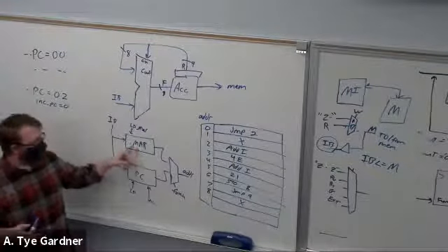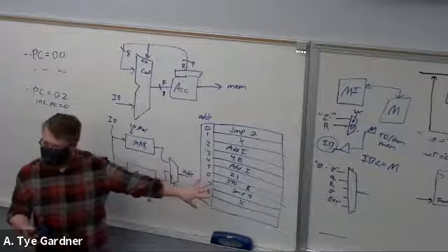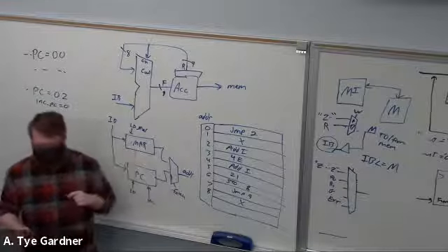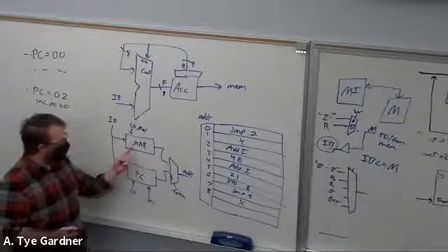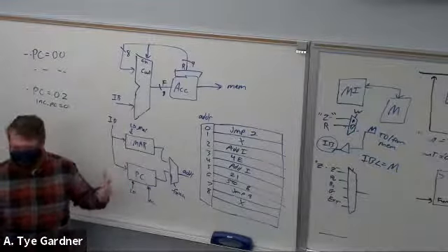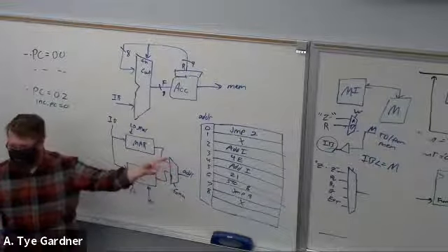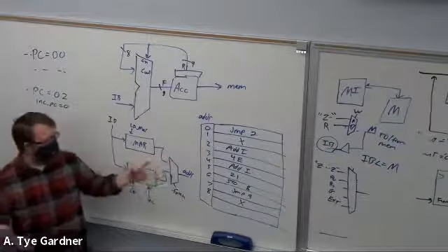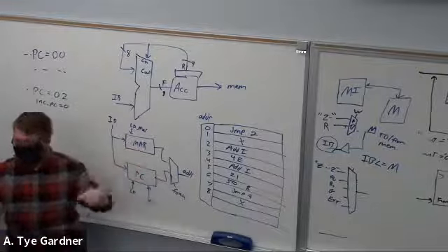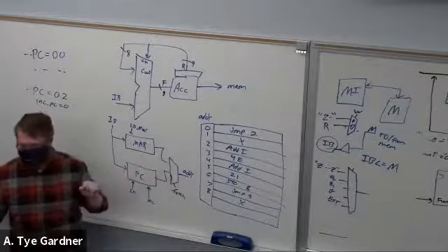And maybe we could also store that address somewhere if we wanted to go back and do it later, right? We can store the MAR if we wanted to. Not from the MAR, we'd have to store it at the same time we put it into the MAR roughly, because the address has no connection to the internal bus. So that's a bit of an issue, but you could store an address that we're going to keep using and just throw the address into memory.